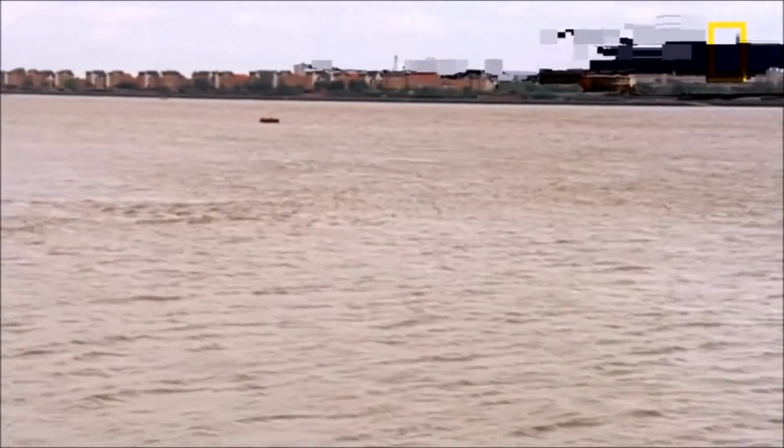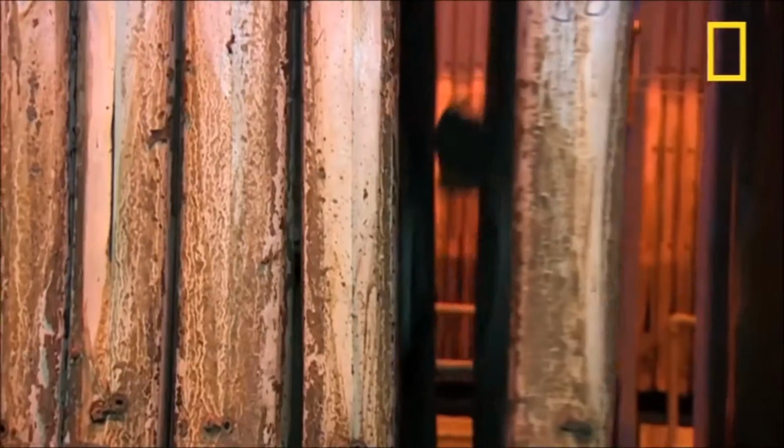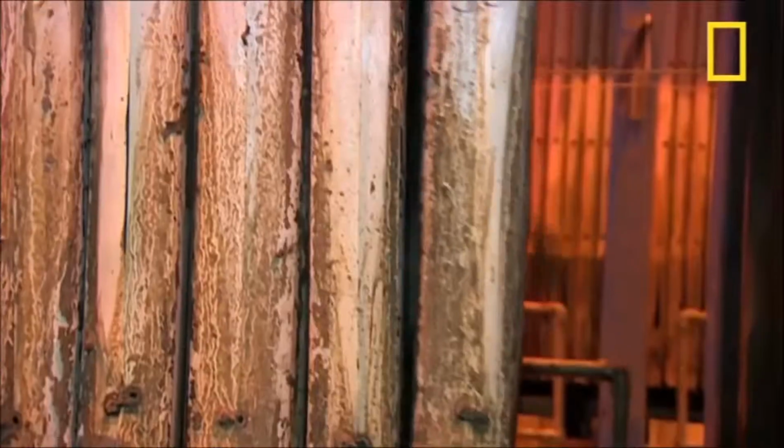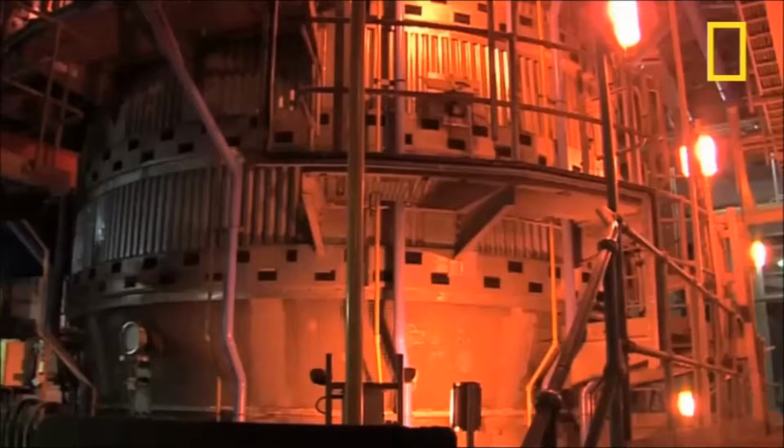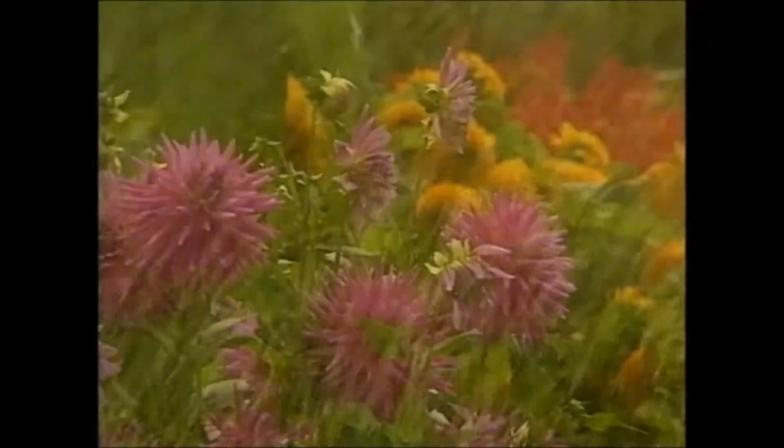Remember all of the solids which were skimmed off earlier? They're taken to a processing plant. All sludges are brought to this filter press where it's dewatered, and the resulting sludge cake is incinerated, and that provides 75% of this entire work's power needs.